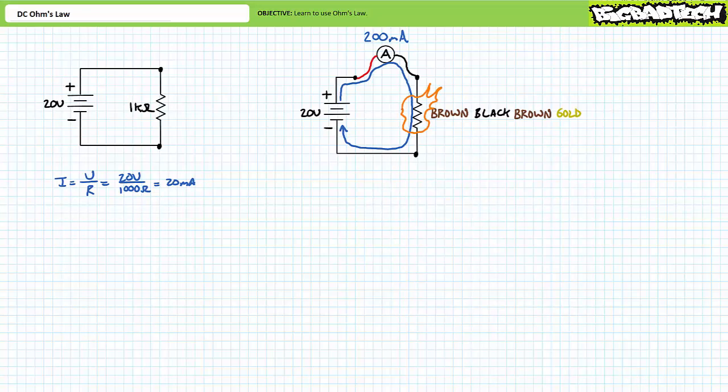The answer is right in front of you if you know where to look. There's really only three elements in this simple circuit: the voltage source, the ammeter, and the resistor, so it's obviously one of these that are at fault. Let's say a quick check of the voltage source with your voltmeter indicates the source really is at 20 volts. What's the problem? It's your lab partner. I warned you about this, didn't I?